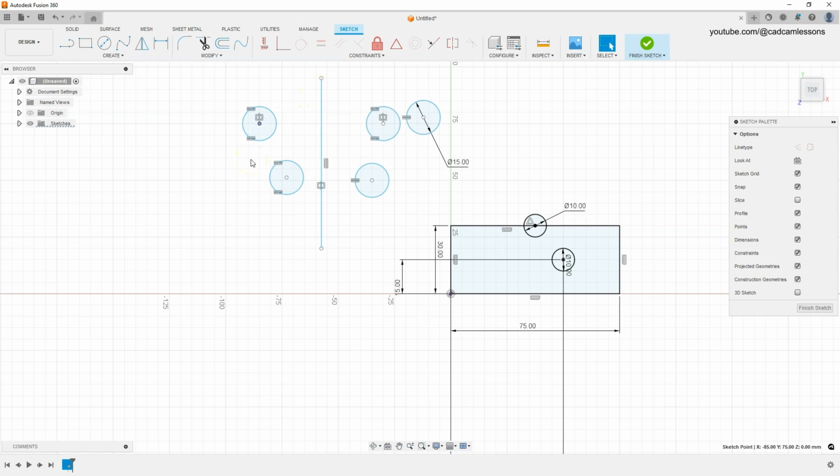And okay, we'll finish here. I don't want to give too much information here. At this point, the most important thing is that you know that there is something like constraints, and constraints create relations between geometries. And allow you to make a connection between geometries and allow you to determine the position of one geometry relative to the other geometry. But we can also get the same using dimensions. However, in some cases, and even in most cases, if we have such an opportunity, it is better to use constraints because the later editing of the sketch will be easier if we have constraints, not dimensions.